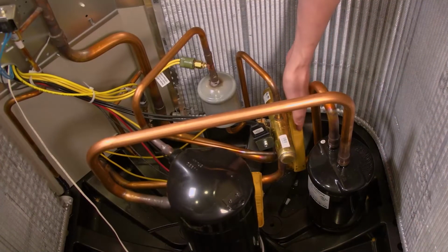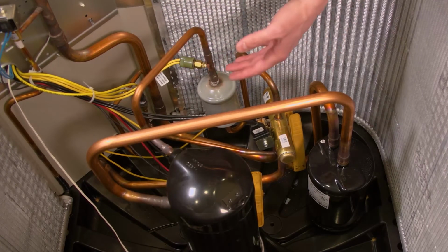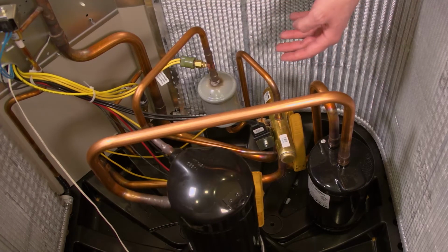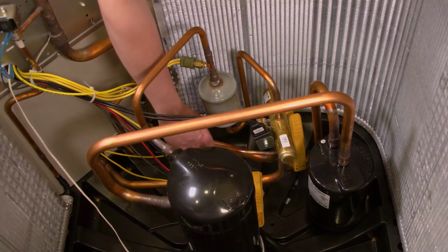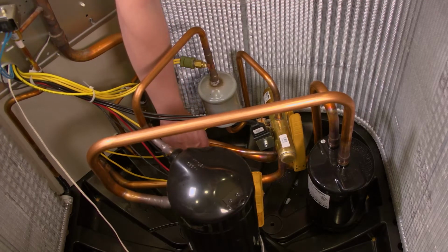Okay, so now we have our clamps installed. So again, we're going to measure our common suction line. And then since we're going to run the unit in cooling mode, we're going to check the line that goes to our evaporator coil. Now, if we were going to test this in heat pump mode, we would basically put our other clamp, this clamp here, we would have placed it on this line because your outdoor coil is your evaporator coil in heat pump mode.